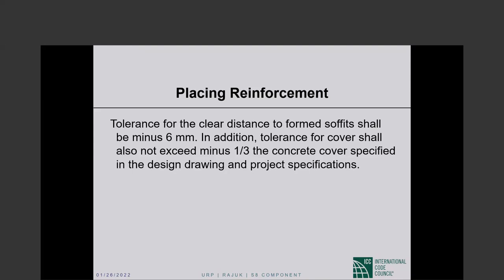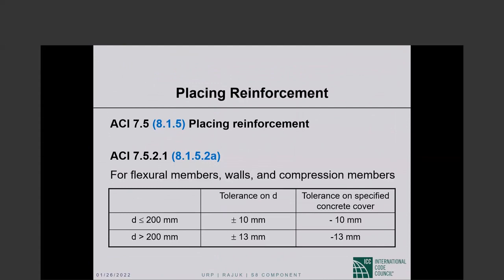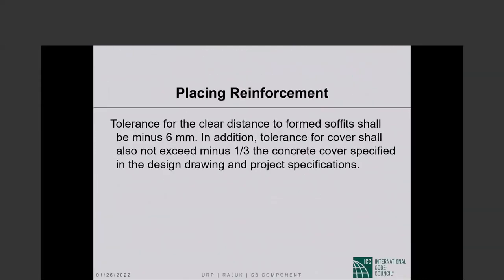In addition, tolerance for cover shall also not exceed minus 1/3 of the concrete cover specified in the design drawing and project specifications. So the minus 10, minus 13 that we had in the table is subject to this further qualification that tolerance for cover shall also not exceed minus 1/3 the concrete cover specified.